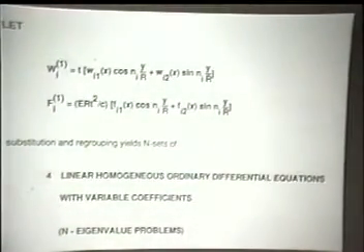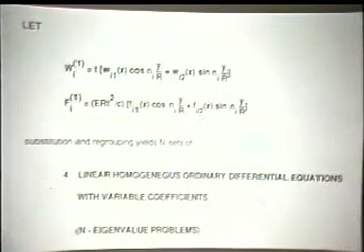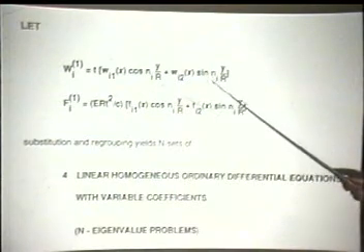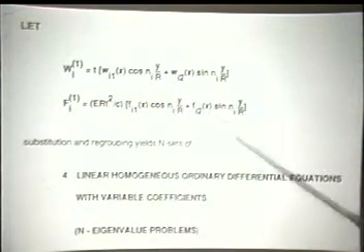I solve the stability equation by this approach. I know that when the shell buckles, I get a buckling pattern with a number of full waves in the circumferential direction, which I can express by cosine ny over r or sine ny over r. I have to have both cosine and sine because the problem is fully anisotropic, to account for the skewedness.